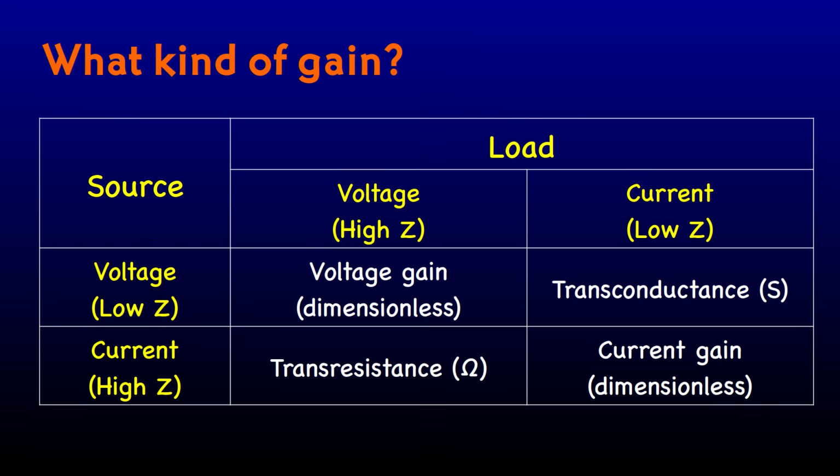Sometimes what we have is a source with an extremely high impedance instead of an extremely low one. These sources will emit a tiny current that might require an input impedance that's unrealistically high in order to show a significant voltage. One way we've dealt with these up to now is to buffer them with a BJT. If we limit the biasing conditions, a common emitter amplifier looks like a current amplifier. The collector current is a constant times the base current. So this circuit is an amplifier with current in and current out. Current gain once again is unitless.